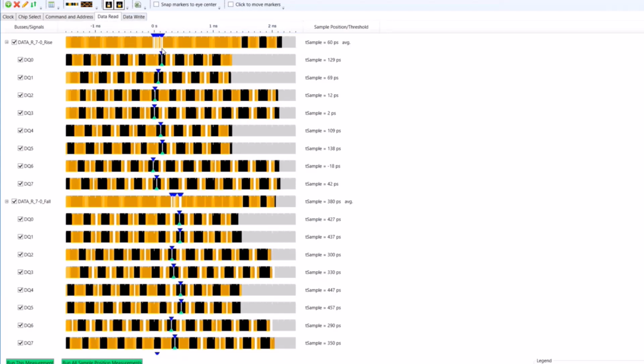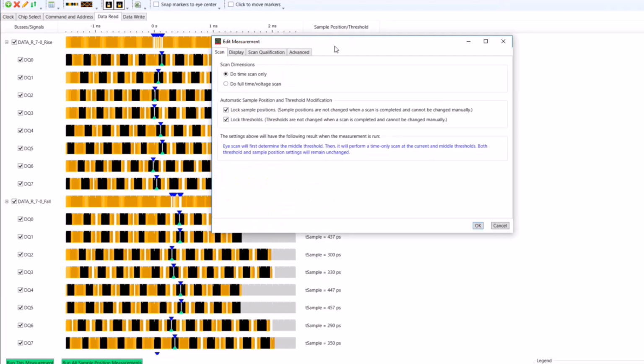Notice we're in the reads, but now the reason we have that signal trace mode is to find the first eye in the burst. Because looking at this when it's in the overlay mode, you couldn't determine which eye to set the sample position in to know which one would be the first. Now it's overlapping all of the eyes. Let's look at what it's doing.